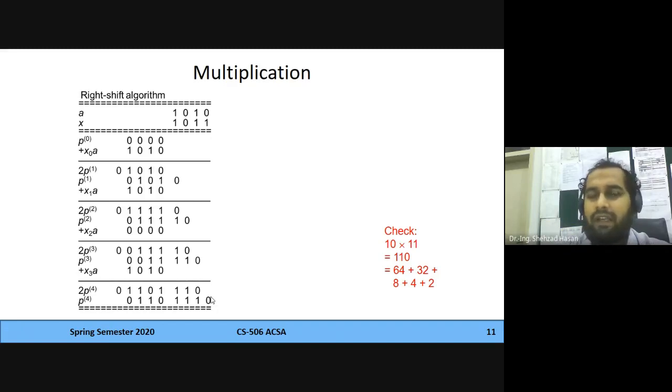It's easy. Whenever there is a 1, you copy the multiplicand, and at each step you just shift the number. What's happening is that when you shift that number, that bit is getting confirmed as part of your final answer. So 0011, a 1 here, 1 over here.